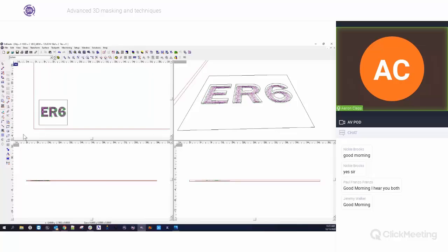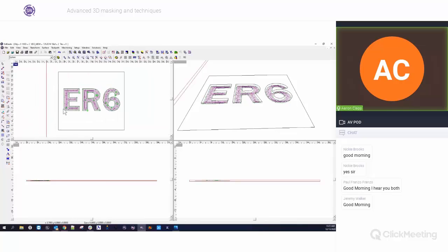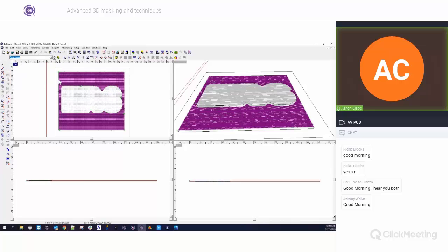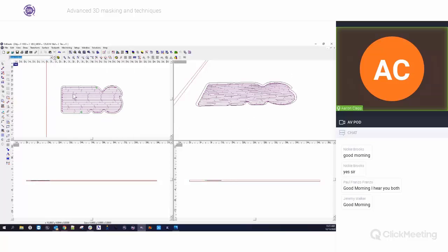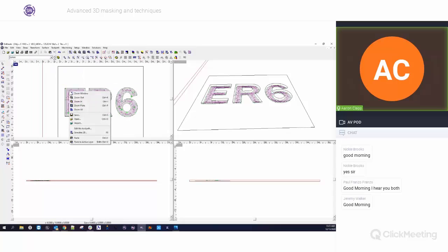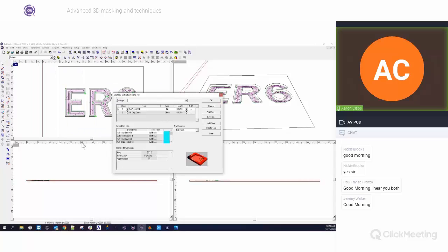Okay, so again, I'm actually not even applying this toolpath in a 3D way at all. A lot of these toolpaths are not. So for the base, this is a 3D cut. We are cutting out the 3D, but this base cut down is just a 2D cut. And so is this letters. It's a 2D cut that I'm using an Engrave toolpath with. So here's what we're going to do. Remember, edit this toolpath. I put two different tools in here.